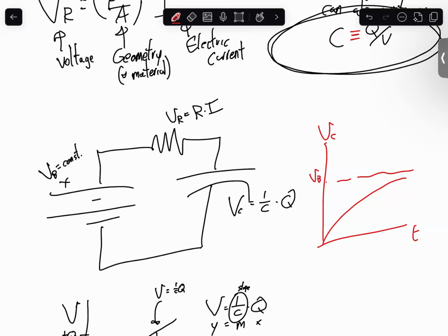What determines the amount of time it takes to get to the output? The resistance and the capacitance. The bigger the capacitor, the more storage it has per volt, so it takes longer to develop. The bigger the resistance, the slower the current flows. As it happens, there's a parameter called the time constant that we may or may not discuss. I don't remember if I put this in the course, which is equal to resistance times capacitance. Those units are seconds. Well, I forget. We'll see if we get there next week.